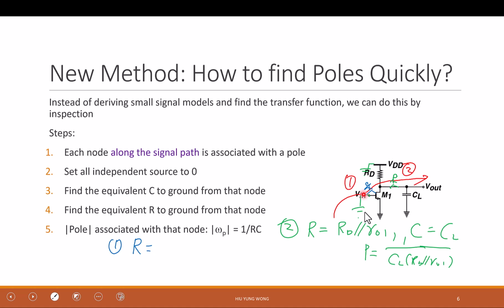I'm standing at this point, right? This is the node, just this line, right? And what is the resistance? 0. And then the mistake I made is, what is the capacitor that will bring me to the ground? Last time I said infinity because I got confused by this curve. But as I just said, when I'm looking for the capacitive path, I will ignore all the resistive paths, right? So yes, this is shorted because of the methodology, but now I'm only looking for the capacitive path.